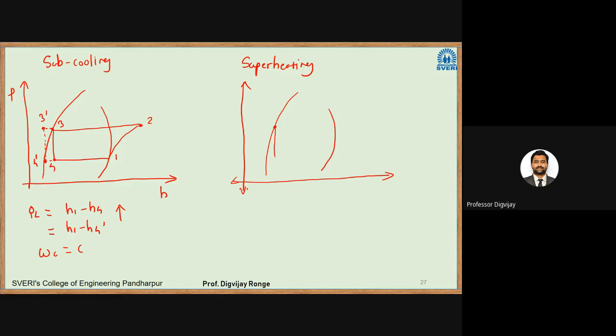First, I will draw that simple VCR cycle. One, two, three, four. Now what I have to do is induce superheated vapor at the start of compression. That means point 1 will move slightly ahead, to somewhere at point 1 dash. Okay. Now obviously when this moves ahead, point 2 will also move ahead, to 2 dash.